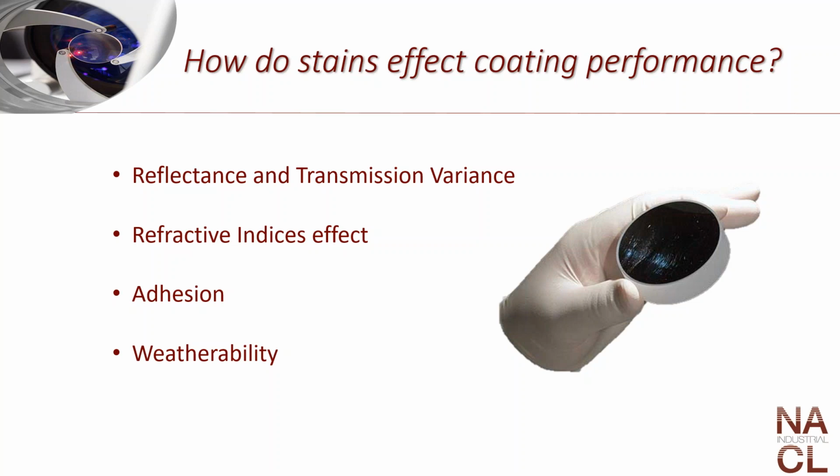Additionally, when a foreign object is on the optic, be it any sort of contamination, that creates a variable for adhesion. Adhesion is basically critical in all that we do. And when there is a foreign object on the optic, the dielectric layers go right over top of that foreign object. This creates stress underneath the film, and that will create what we call a pinhole, or will start breaking away the base adhesion layers of the coating, creating an adhesion issue or adhesion failure.